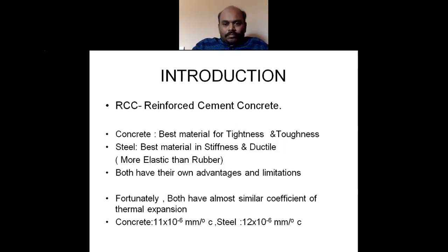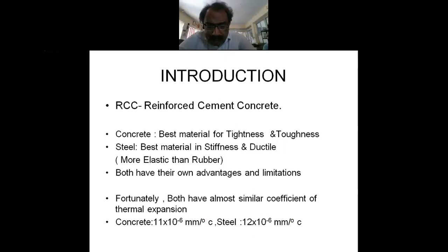We maintain 20 to 25 degrees Celsius. It will not be air conditioned. Our normal climatic conditions are 40 to 45 degrees Celsius in summer, and 20 degrees in winter, going down to perhaps 5 degrees in December. So 20 to 25 degrees into 10 to the power minus 6 into 11 or 12, that much of elongation and contraction occurs in the building with respect to the season and the temperature variation within the building.